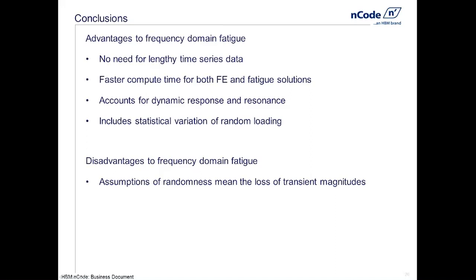The problem with average amplitudes is that we're losing bigger loading cycles and bigger stress cycles as a result. The problem with using the peak loading information, if we chose to calculate what we call a peak hold PSD, that's a reasonable thing, but it's hard to use in fatigue because that then says that every cycle that ever happened was however big the biggest cycle ever was.